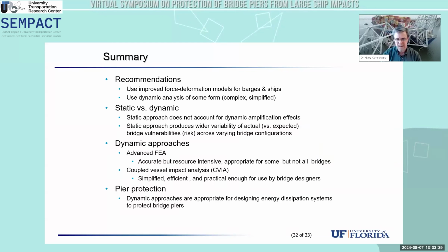Static versus dynamic: the static procedure does not generally, or at least does not rationally, calculate or capture dynamic amplification effects. Again, we can try to empirically capture that, but it's fairly challenging to do so. And as a result of that, the static approach tends to produce a wider range of variability between what we expect to be the vulnerability of a bridge and what the actual vulnerability is if we look at it dynamically. So there's a much greater spread in terms of the risk level across a large number of bridges, and that's as a result of the differing dynamic characteristics of bridges.